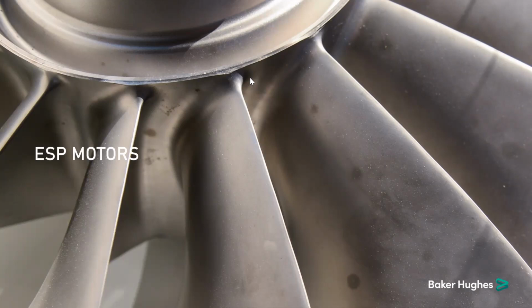So there is no risk of having the well fluid inside the seal section unless the labyrinth section goes completely filled with the well fluid. Then it will go to the second chamber and there is danger of contamination with the motor oil.